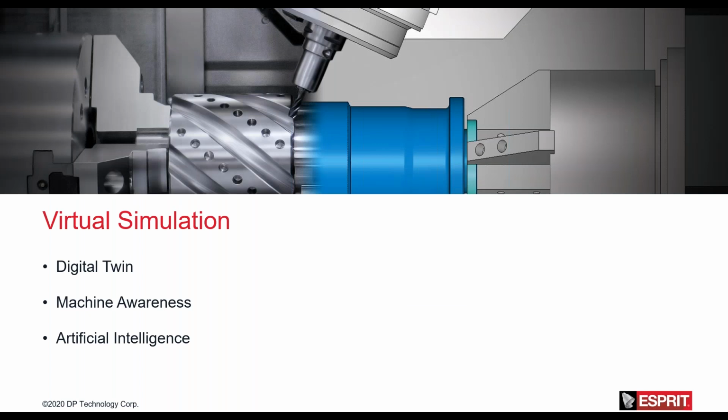Why do you want accurate representation for your tooling? The newest version of ESPRIT uses the virtual machine definition to construct artificial intelligence, which is used to make decisions for the programmers, linking movements like positioning between cuts and operations. They are produced automatically by the software based on the machine kinematics and travel limits defined in the machine setup.